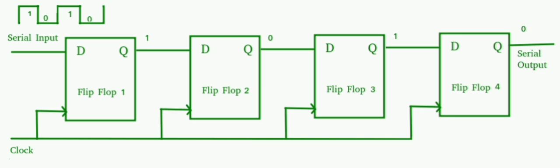Here the op amp is employed as a summing amplifier. The op amp is used in negative feedback mode to work as a current to voltage converter for an n-bit DAC. Number of different levels = 2^n. Number of steps = 2^n − 1.